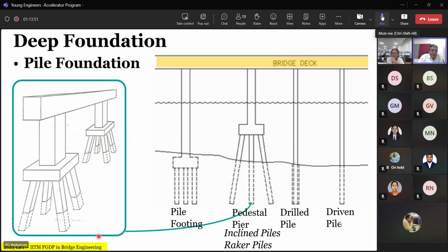So now what do we do? Lateral raker piles are very good for taking large lateral forces, but in seismic conditions, I don't want very large stiffness. Our engineer's life is very miserable, right? The solution that is most suited for large forces is very bad for earthquake conditions, which produce the largest horizontal forces. Correct?